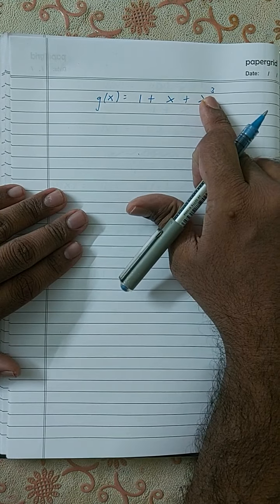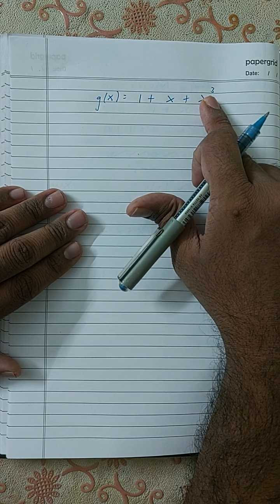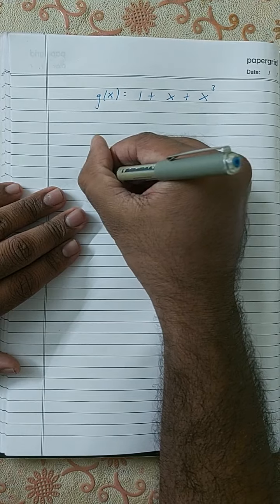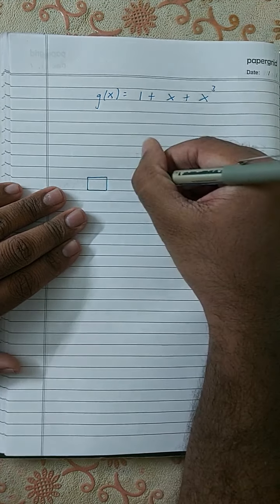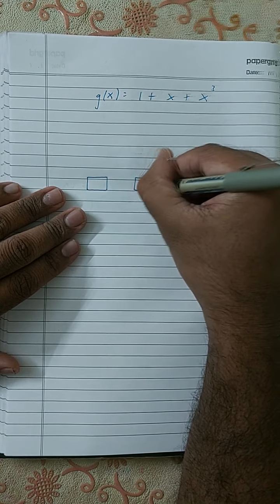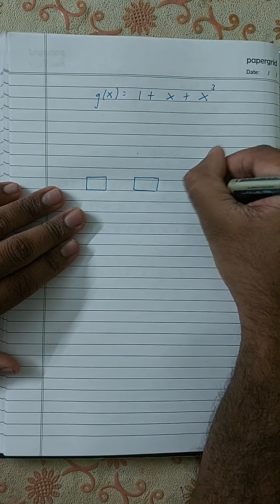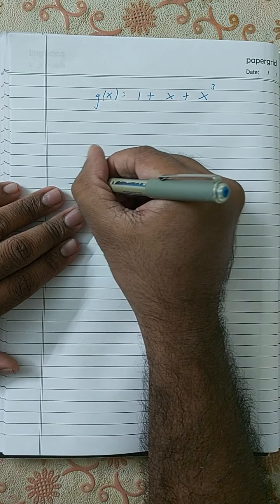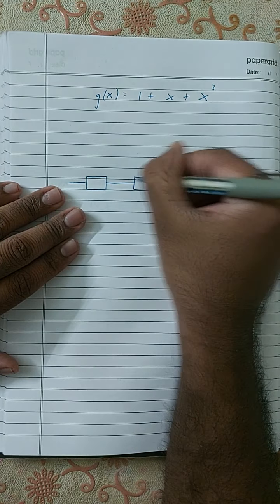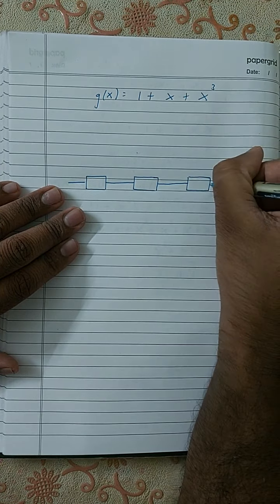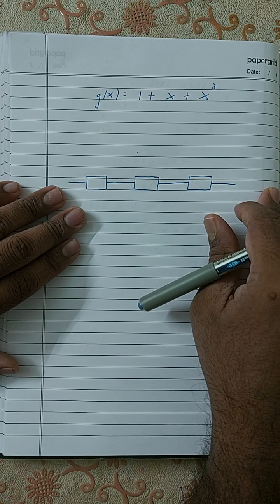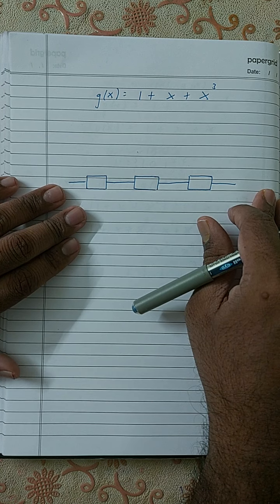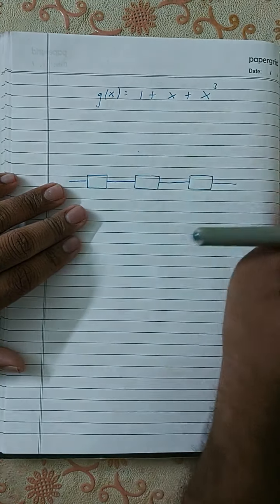So this is how I'm going to draw. First I look at the degree. Degree is how much? 3. So I'm going to draw 3 shift registers. 1, 2, 3. Okay, I draw 3 shift registers, and then I will draw the input of all of them. I will connect all of them over here like this. Okay, and then I'm going to draw the switch. Now how will I draw the switch if you ask me? That depends on the value of the coefficient.